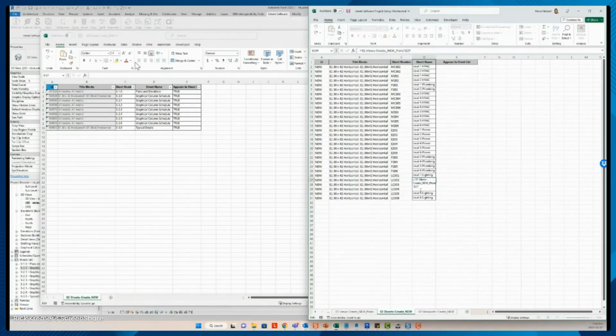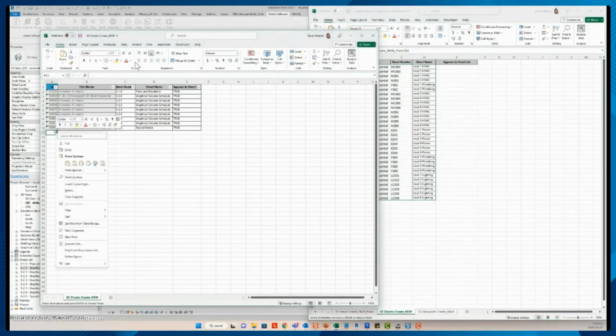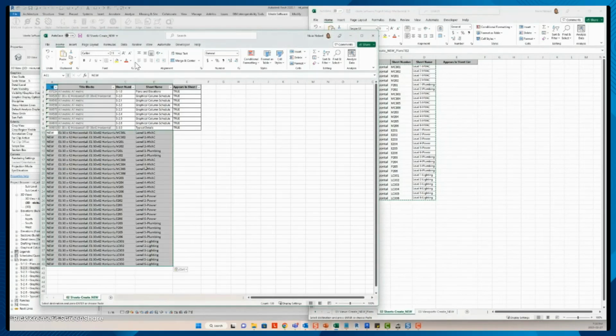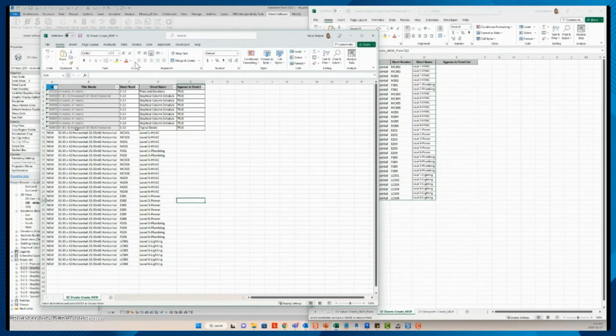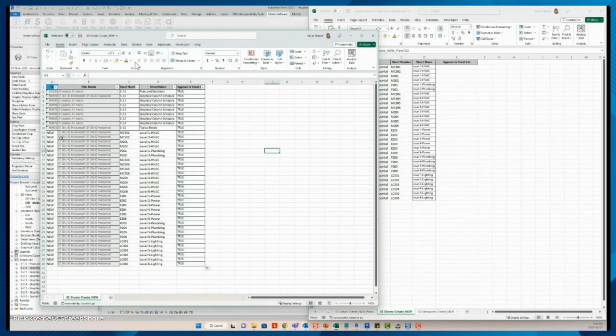All the heavy lifting has already been created here, including all of the formulas built into Excel. I don't have to do anything. Here, the only thing I need to do is copy the information from Excel and then paste it into the new Excel spreadsheet. I'll paste the information and now highlight the whole thing. Here, I'm going to basically use simple Excel to copy the information of my formatting for my sheets. Here, I'll simply drag the formatting from my existing sheet and copy that down to my new sheets using Excel. Next, I'll go ahead and apply a true statement, which is going to tell BIMlink to go ahead and create these new sheets for me. Here's the list of all my sheets, 30 by 42.